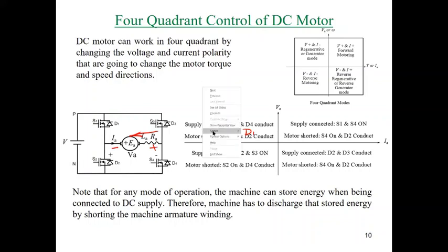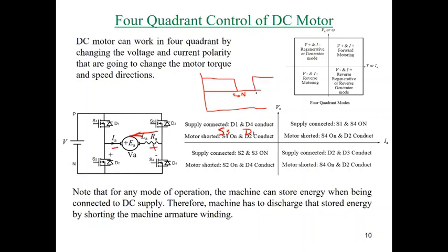In terms of DC chopper, we described before in the last class, if we have a DC chopper like that, if we apply a pulse during T on, and this is the full cycle. So this is a pulse. If we apply the pulse to the switches S2 and S3 together, the voltage will be the applied voltage V, if this is V capital, and this is V A.